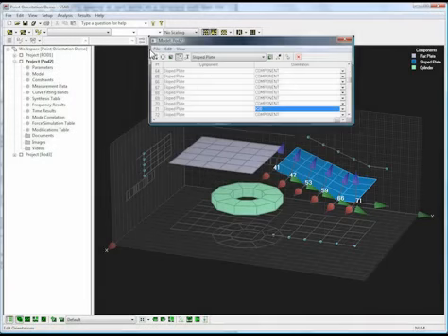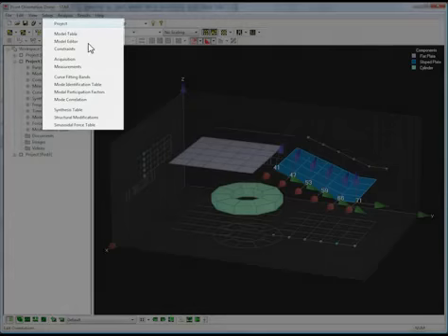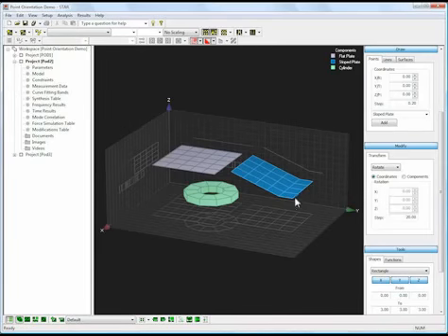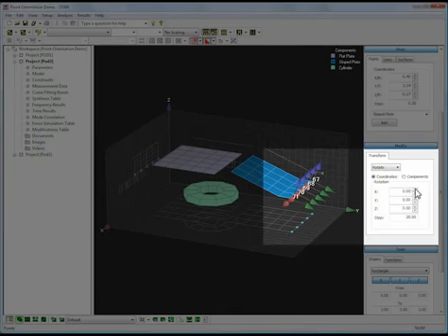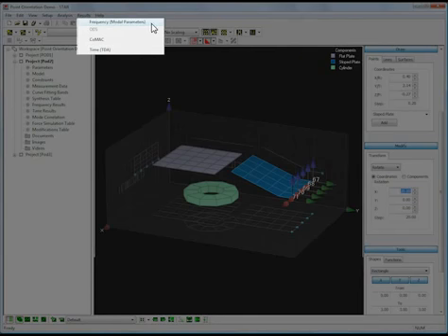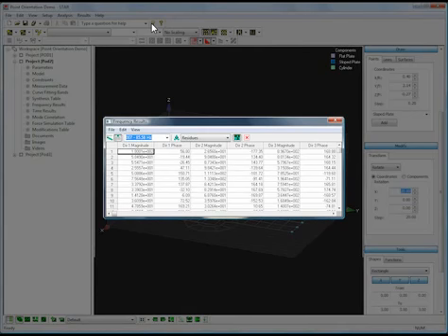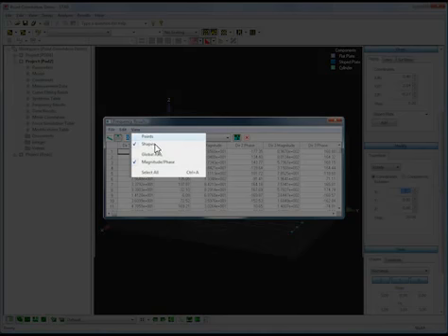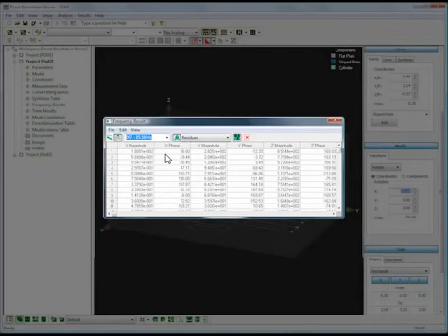Using the interactive editor, the local axis for groups of selected points can be adjusted visually with ease. Once the local axis for each point is correct, the model can be used as a guide during acquisition for correct placement and orientation of the transducers. Data is acquired in terms of a local axis, but once the data is analysed, the modal parameters can be displayed in terms of its original local axis or the global axis.